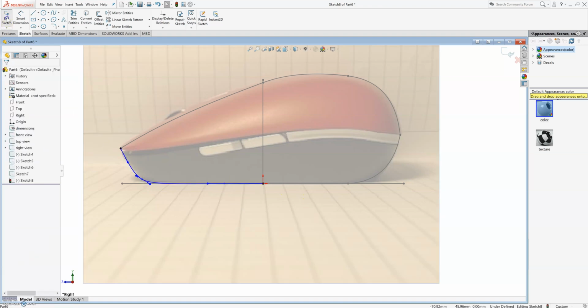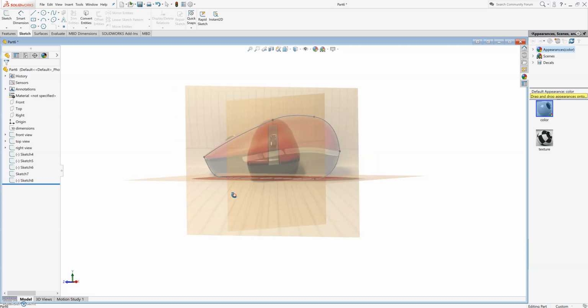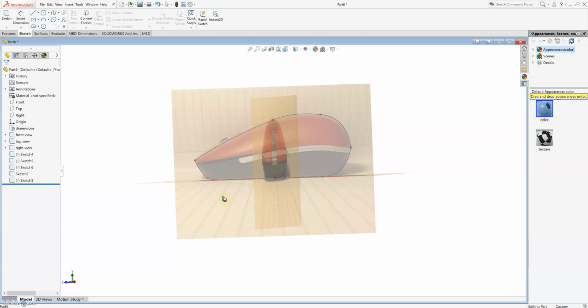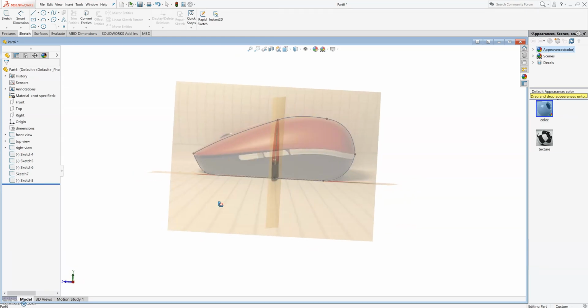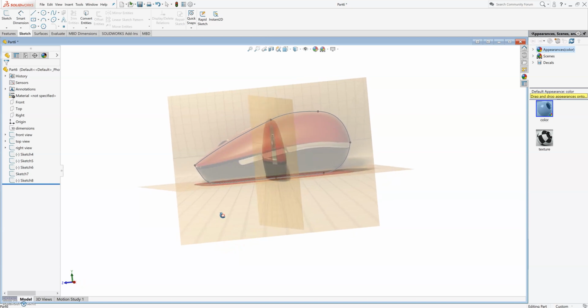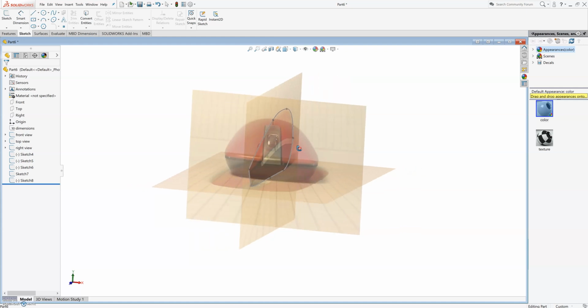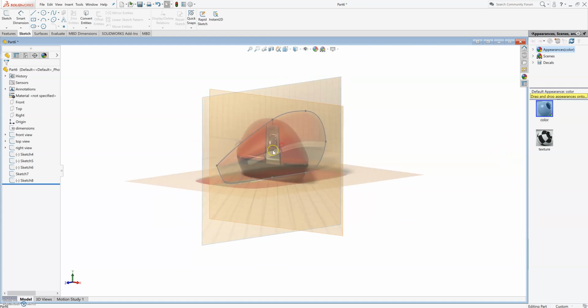So now we have a total, I'm going to hide our dimension sketch. We have 6 separate lines now that are kind of shaping the middle part of our plane here. This is going to be really helpful down the line, so that when I actually finish putting all my other lines in here, then I can just close this off and create a solid body from it, which is our ultimate goal when we're making surfaces.